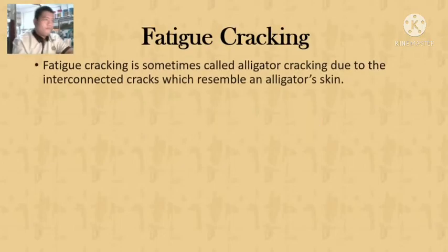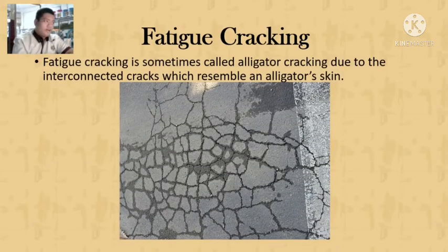First is fatigue crack. Fatigue cracking is sometimes called alligator cracking due to the interconnected cracks which resemble alligator skin. Fatigue cracking is caused by load-related deterioration resulting from a weakened base course or subgrade, too little pavement thickness, overloading, or a combination of these factors.